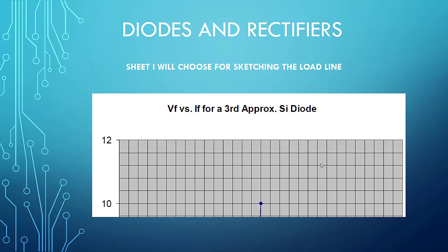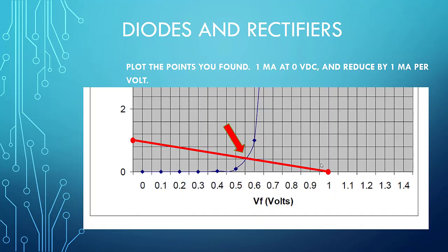So I'm going to find a sheet for my silicon diode that has my best range, and I know that I'm in the 1 milliamp range, so I'm going to pick the closest one that gives me the most resolution. If I picked the 120, it would be so small I could hardly tell what was going on. So I go on the left-hand side and find my 1 milliamp. My divisions going up are 0.4, 0.8, 1.2, 1.6, and then 2.